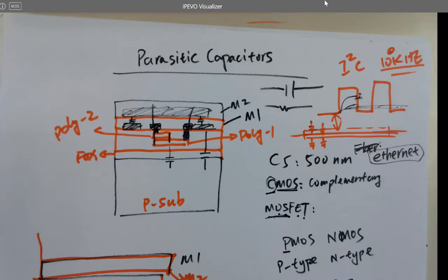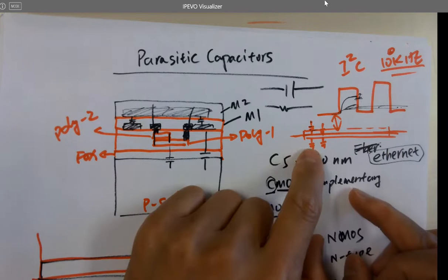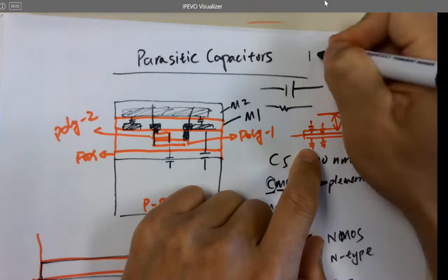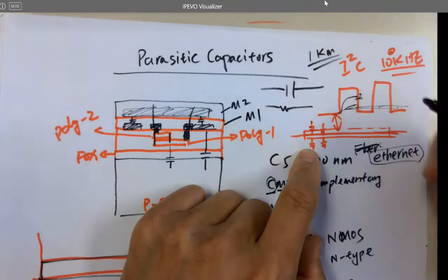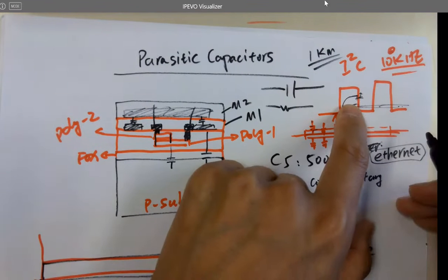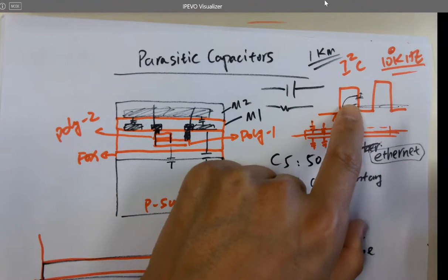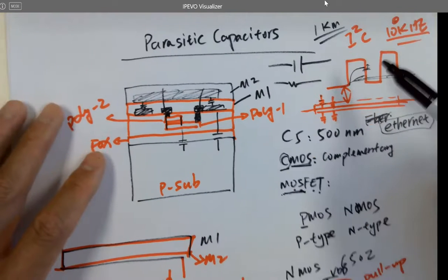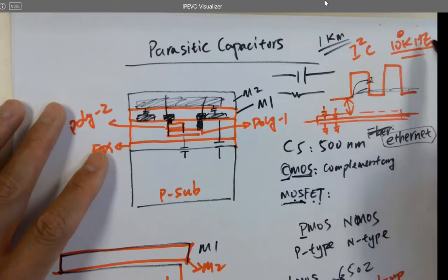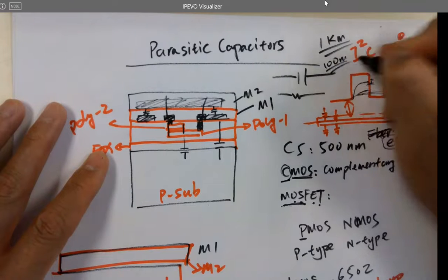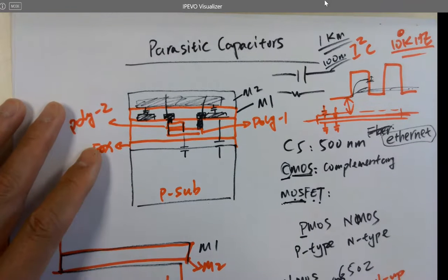So these cables are a little bit special. They engineered it to make it a lower parasitic capacitance, but still you cannot have a 1K, 1 kilometer long. It's still going to attenuate the signal a lot. But what I have researched online, the result shows for 100 kHz, for example, somewhere around 100 meters is still fine, which is good enough for their property.